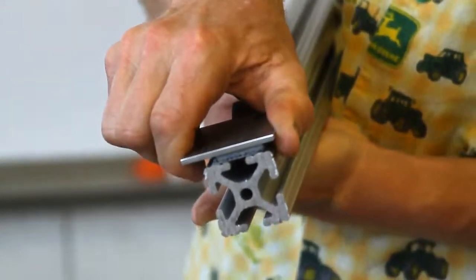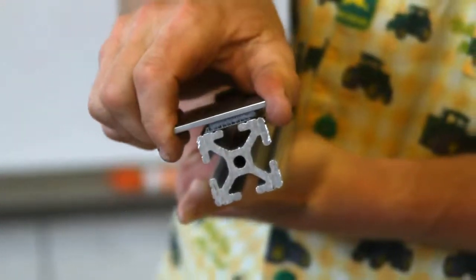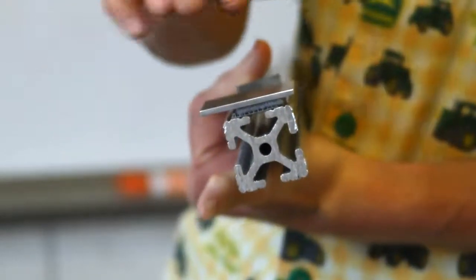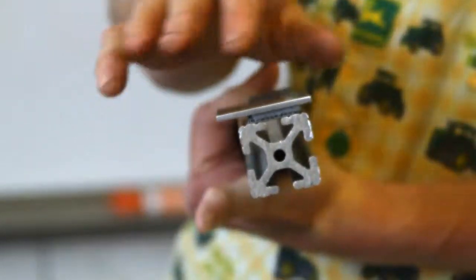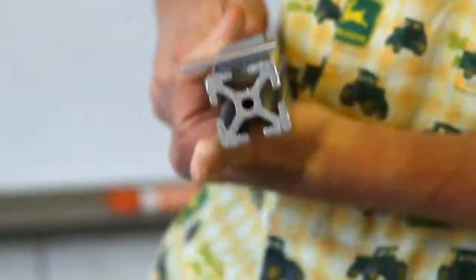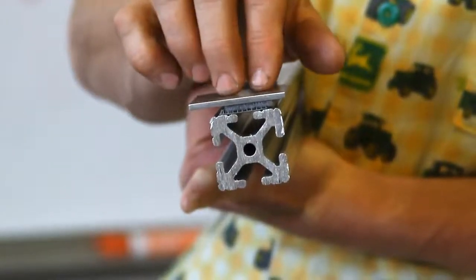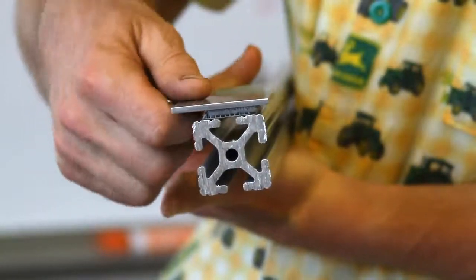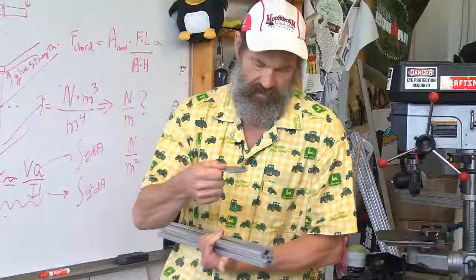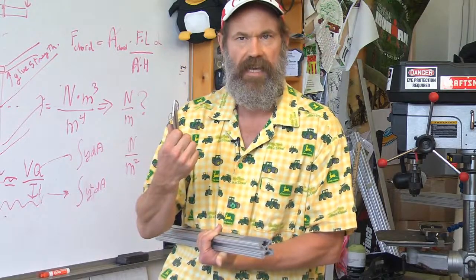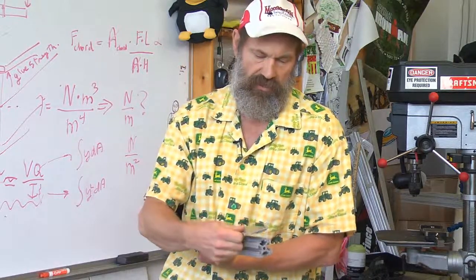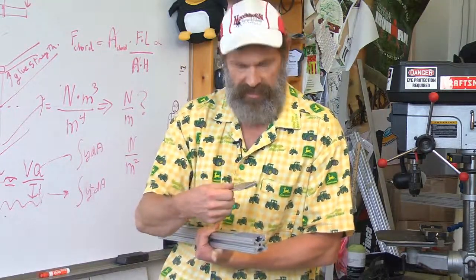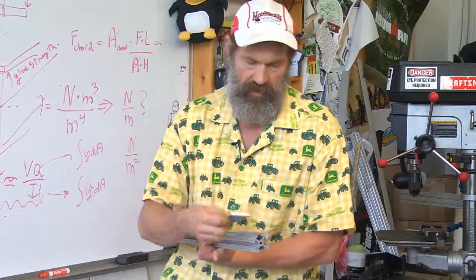The little bit of compliance it does have will stiffen this. It won't necessarily add to the static strength so much. It'll help a little bit, but it'll really stiffen it. And then I can remove it if I need to gain access later. In other words, the peel strength is much less than the shear strength for Velcro.